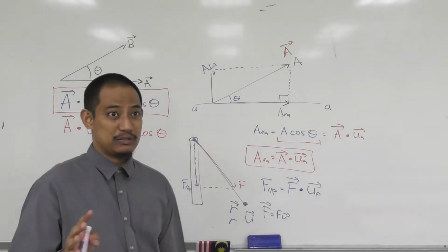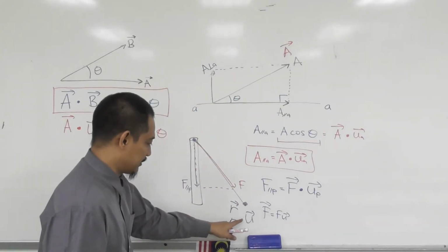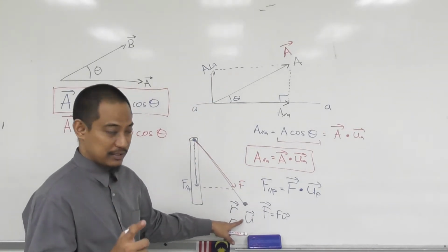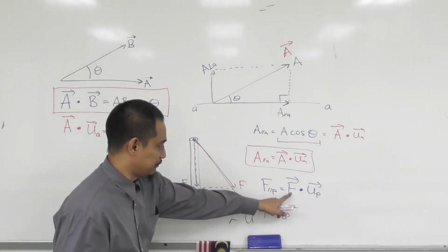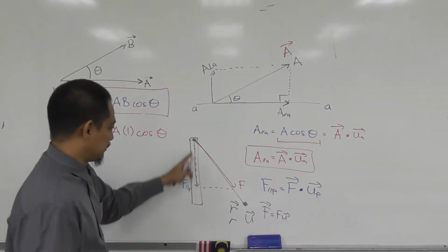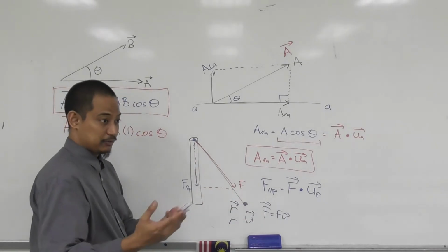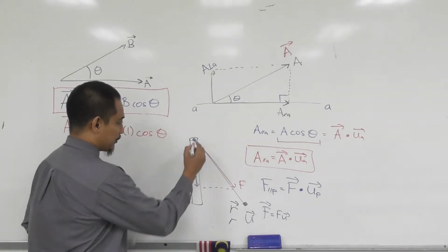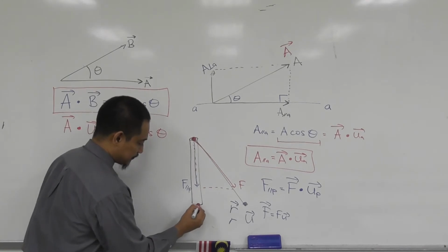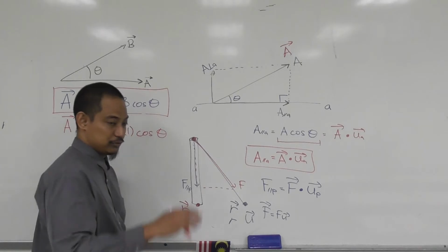And make sure you understand unit vector of what, because the one that I just said is the unit vector of this line, that is for this F. This unit vector is for this different line, right? So how do we get this unit vector? Still, you can use the same understanding as before, right? If I know this coordinate and this coordinate, I can get r vector. If I know r, I can get r magnitude, square root.